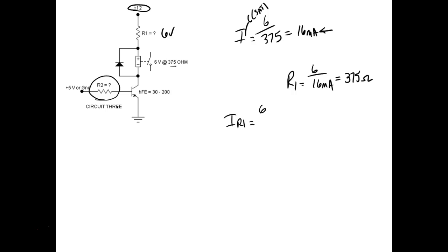So you can get your ohm meter out and measure across the connections to the relay coil, not the contacts, and measure if it's not specified. On a DC relay, they might just give you the voltage. They won't give you the watts. They won't give you the ohms.